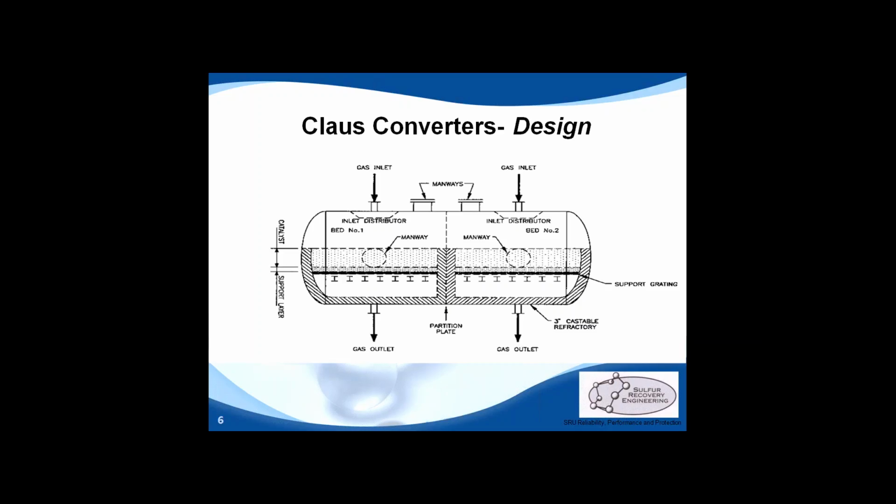From field experience, especially in Alberta, where the overall sulfur loading or sulfur levels or load to the SRU is declining due to wells that are becoming less sour, so less H2S overall, operators struggle with oversized converters and achieving desired conversion or recovery levels. Inlet distribution is very important such that we maximize the available amount of surface area for the reaction to take place. We see that we have a bed of catalyst supported by grating. Sometimes above the grating, we will have inert substances, or balls, to help with the distribution of gas outside and exiting the Claus converter.